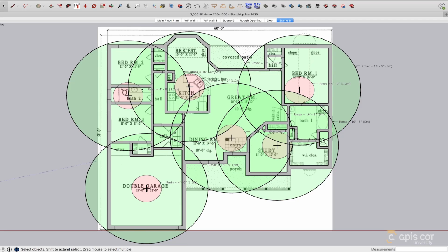Finally, we can break the building up into multiple sections, define which walls will be printed at each position, and determine the order in which the sections will be printed. Again, this process can take some trial and error, but let's try to start with this section at the back corner of the home as our first position, seen in red. We will leave one portion of the wall open so the printer can easily drive to the second position near the front of the home, seen in orange.